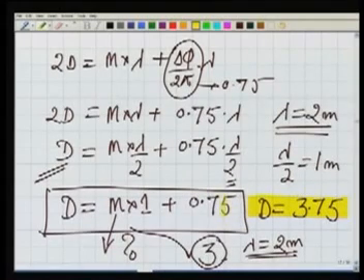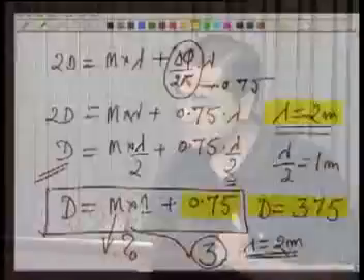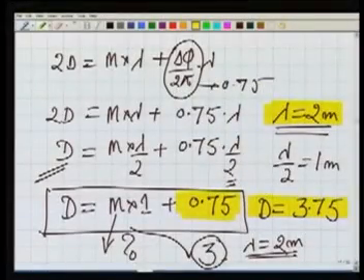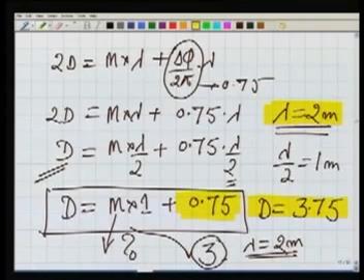We are using this 7.5 from lambda is equal to 2. Why? Because we have seen already that the phase difference can be measured with a certain least count, and this least count or resolution is better if the lambda is smaller. So because of that reason, this 7.5 is measured more accurately, more precisely than in the case when lambda was 8. Now here, because the lambda is smaller, lambda is 2 meters.